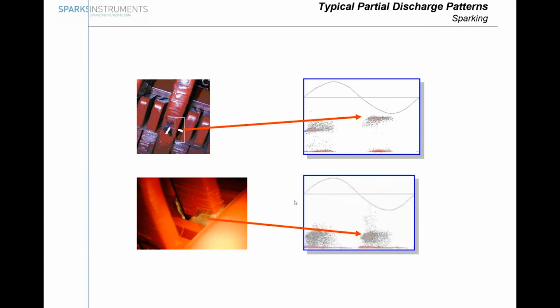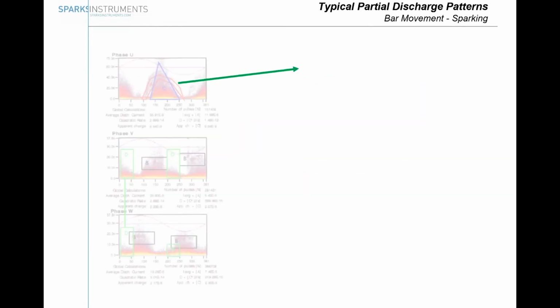Here on this bottom side was a defect using a wrong coating at the slot exit. So we have here the slot exit bar and the pressure finger, arcing between the pressure finger and the bar. Also here making clouds. So whenever you have a cloud type, this is some kind of arcing.